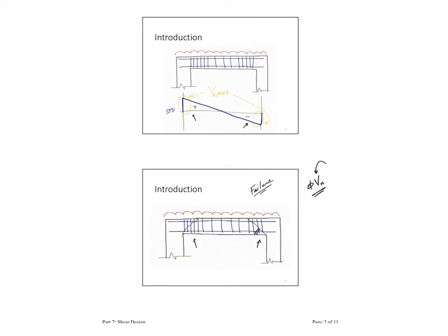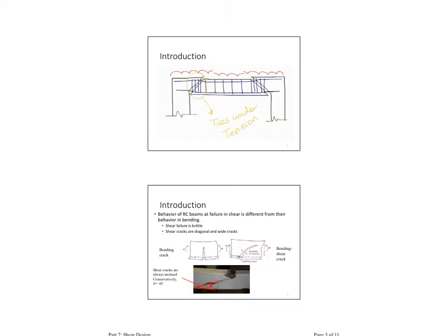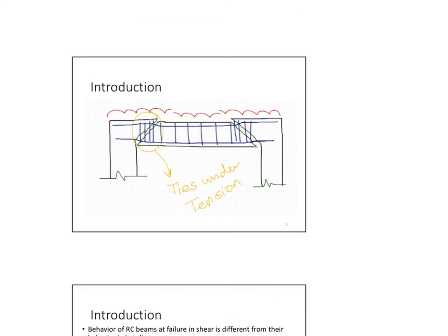If we take one of those small elements, as we will describe now, here, if I take an element that was pretty much in this place, the shear stresses look something like this, over here and over here. This is how the shear stresses look like. I'm taking that out here, and due to equilibrium, this piece of concrete, or the element, will not rotate. And the reason why it's not going to rotate is that there is a coupling force that resists this rotation.